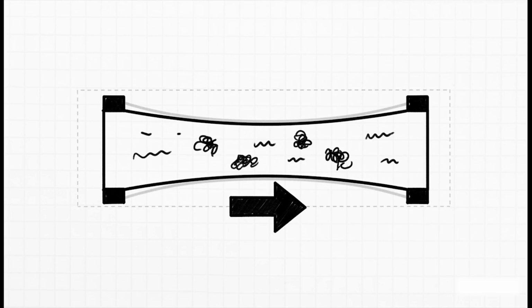Then there's the non-uniform distribution of the lateral load-resisting system, the LLRS. Now, this one's a little more subtle. Imagine a long, skinny building, and the only strong shear walls are way out at the 2 ends. During a quake, the floor slab in the middle has to drag the seismic forces a huge distance to get to those walls. The center of the building starts to bow and deform, putting all this unplanned, intense stress on the columns stuck in the middle.